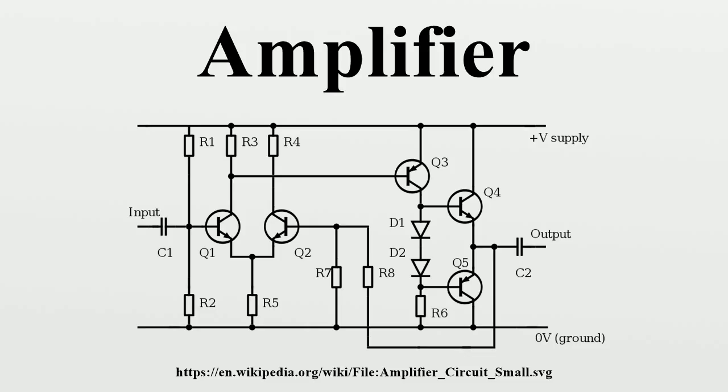Power amplifier. The term power amplifier is a relative term with respect to the amount of power delivered to the load and/or provided by the power supply circuit. In general, the power amplifier is the last amplifier, or actual circuit, in a signal chain and is the amplifier stage that requires attention to power efficiency. Efficiency considerations lead to the various classes of power amplifier based on the biasing of the output transistors or tubes. See power amplifier classes.